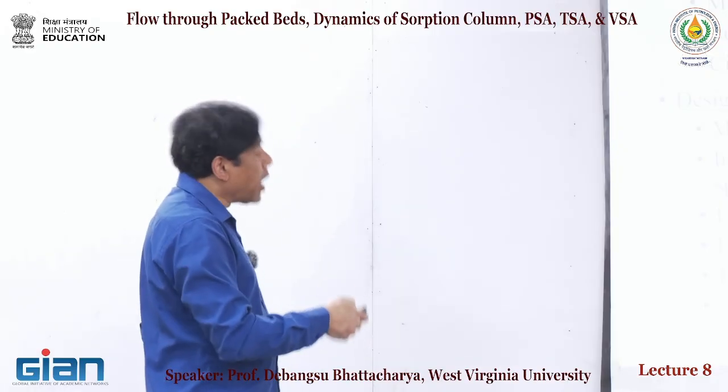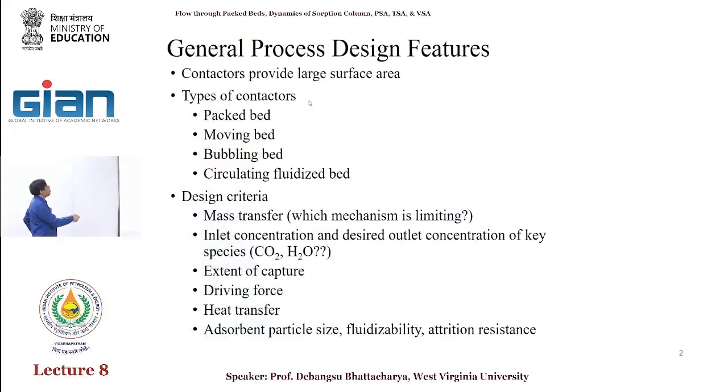The other thing is that if you are using a bubbling bed or fluidized bed, you have to think about the fluidizability of the particle, right? If your particles break apart when they hit each other, then that type of particle is not good to be used in a fluidized bed. Because in a fluidized bed, the particles will collide with each other and they can break only to some extent, but they should not break into small pieces, because then you cannot keep them inside the bed. They will be carried away with the gas from the bed.